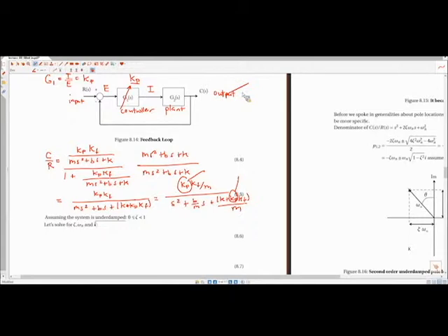I just realized that maybe we should clarify this. We have a term in our feedback loop called the input, or the input to the plant. But every single system has a defined input and output. So the input to the plant is U, or more generically call it U. But also if we look at this transfer function, and we want to write the transfer function from R to C, transfer functions are output over input. So we're looking at this transfer function C over R.